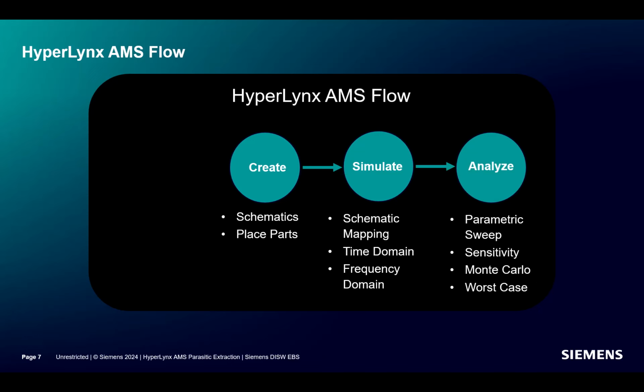In the analysis stage, we can perform a variety of different analyses including sweep, sensitivity, Monte Carlo, and worst case. The analyzed data is loaded into the waveform analyzer to view and measure performances, tolerances, and variations.